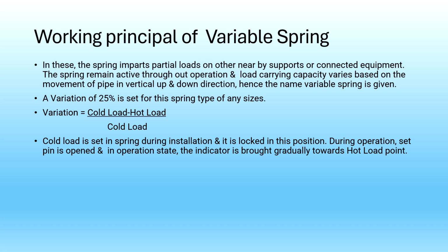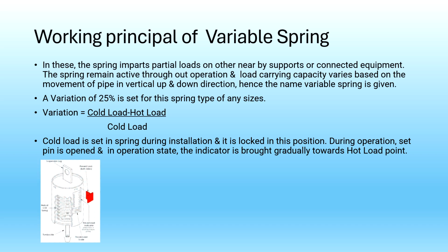During operation, the set pin is opened, and in the operation state the indicator is brought gradually towards the hot load point, that is, during operations it will normally come down to that particular point. Here we can see the indicator will be there, and this will be the stopper. On the spring there will be a preset pin, which will be inserted during installation, and we will remove it when the spring is completely installed.